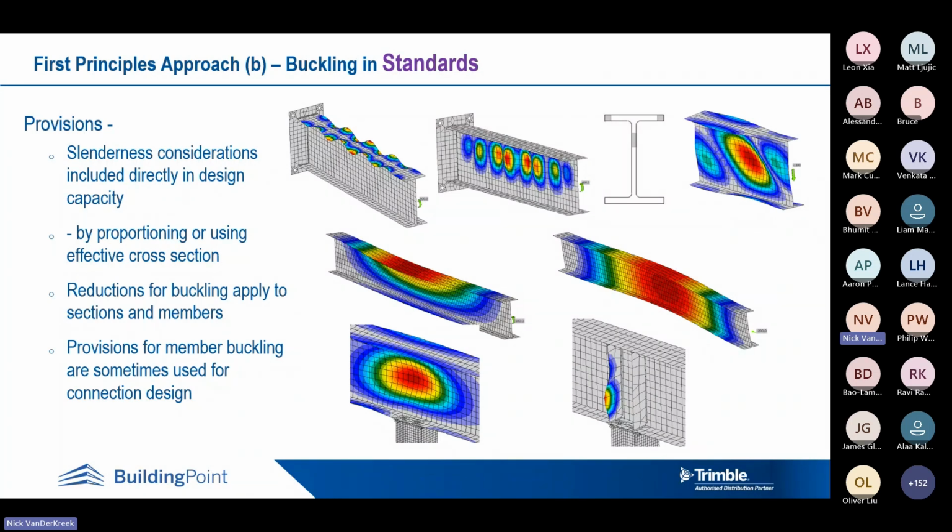And in fact, in a later example, I'll show a consideration, in a sense, of gusset buckling as a member, in a short region. And also, if you have a knee brace, a short member in the connection, then member buckling could, of course, come into it there. But mostly we're concerned with short regions of members in the connection vicinity, a shear panel or something like this, and we are more concerned with local buckling on this topic. Sometimes the other buckling considerations, of course, including member buckling, come into connection checks, such as bearing checks and stiffener checks to the code.